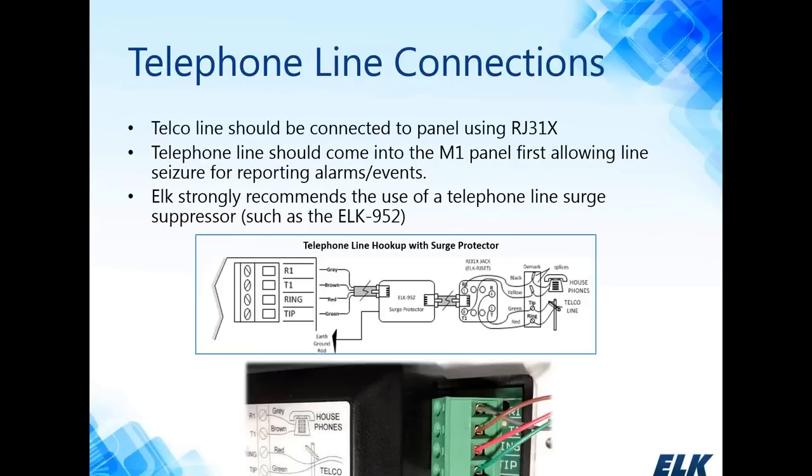Now the M1 is always connected to the phone line. It's always monitoring the phone line. So through the automation rules, we can tell when a phone goes off hook. We can tell when the phone is ringing and things like that. So the M1 is constantly monitoring the phone line. And because it's always on the phone line, we highly recommend that you incorporate telephone line surge suppression into your install.